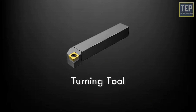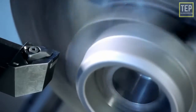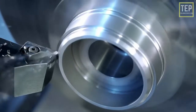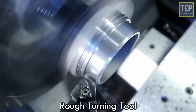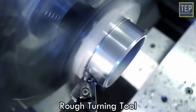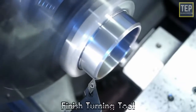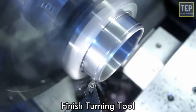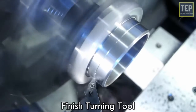Turning tool. There are mainly two classes of turning tool: rough turning tool and finish turning tool. The main function of a rough turning tool is to remove the maximum amount of metal in minimum time that the tool, work, and the machine will permit. The cutting angle is ground so that it can withstand maximum cutting pressure. A finish turning tool is used to remove a very small amount of metal. The tool angle is ground so that it can produce a very smooth and accurate surface.